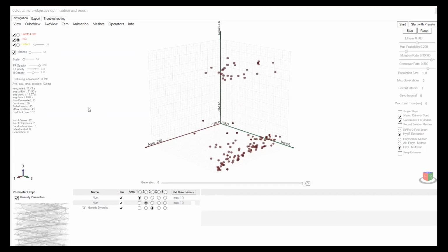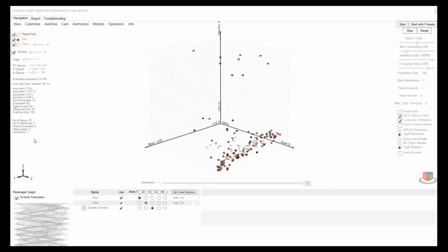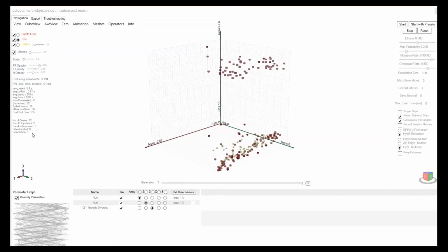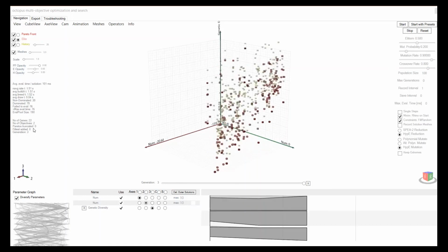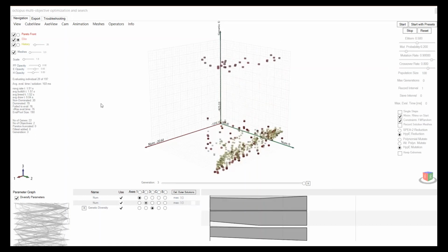So now it's evaluating individual solutions and creating multiple generations. It created one generation right now. When we say generation, it obviously does not mean just one design solution, but hundreds and thousands of solutions. Then it minimizes them, does the crossover and the mutation, and picks the more ideal solutions that can survive.